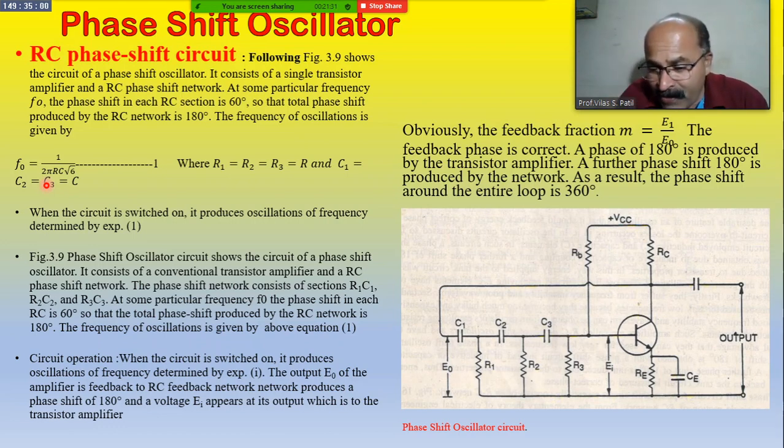The second one is the transistor amplifier, and we know that the common emitter transistor amplifier mode is used. Here the potential divider is formed by RB and R1. See, this is RB, and R1 and R2 play the role of potential divider. This is the collector output resistance RC, and this is RE and CE, the emitter resistance as well as the emitter bypass capacitor.